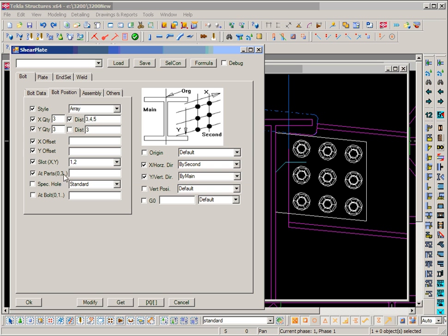And the next line is which parts have this slot or oversize. This starts from 0, but this part is not like Tekla, which counts from the bolt head. This is the order you gave in the connection builder. Which part is the bolt part? The order is per the order you gave for the bolt part.